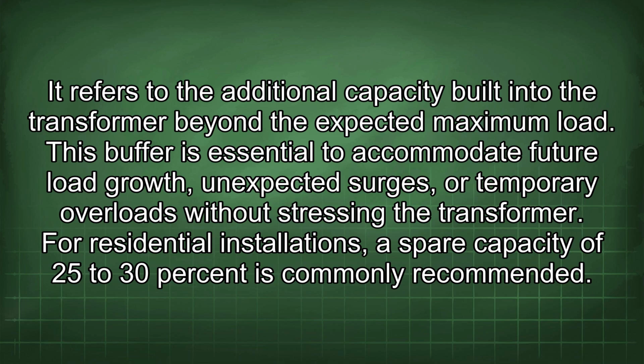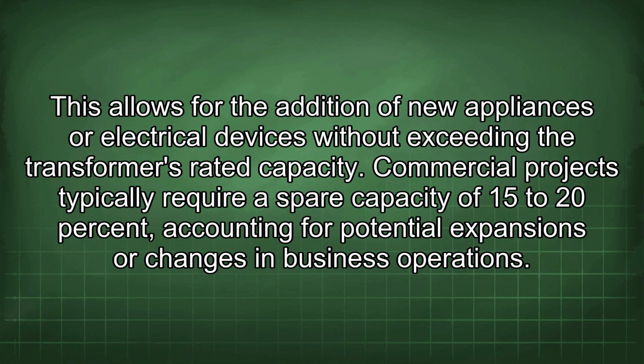For residential installations, a spare capacity of 25 to 30% is commonly recommended. This allows for the addition of new appliances or electrical devices without exceeding the transformer's rated capacity. Commercial projects typically require a spare capacity of 15 to 20%, accounting for potential expansions or changes in business operations.